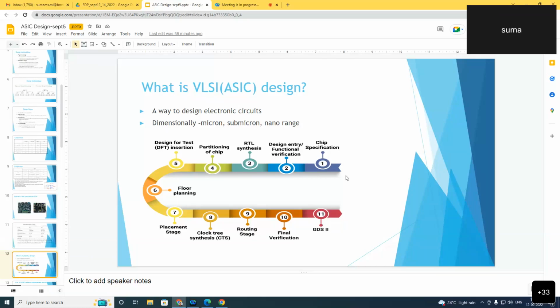So the dissipation is huge during this cycle. And depending on the rate of the transition, short circuit current also contributes to the power dissipation. This kind of power can be optimized by ensuring minimum switching, which can be accounted for at the architecture level. So we will see how that will be done in the afternoon.